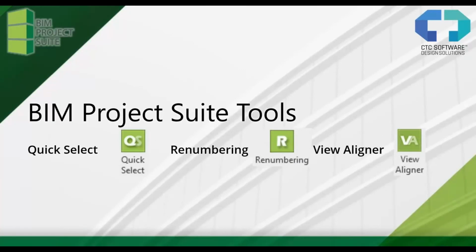The first suite that we are going to look at is the BIM Project Suite, and there are three specific tools in this suite that I want to talk about today. It's Quick Select, Renumbering, and View Aligner. Quick Select has been around for a while, but it got a facelift this last year. Basically, what Quick Select is, if you remember AutoCAD, you had a Quick Select feature where we could quickly input some criteria and get a selection of items. That's exactly what it is here for Revit. And then we can build upon that, save those settings, and use them on other projects.